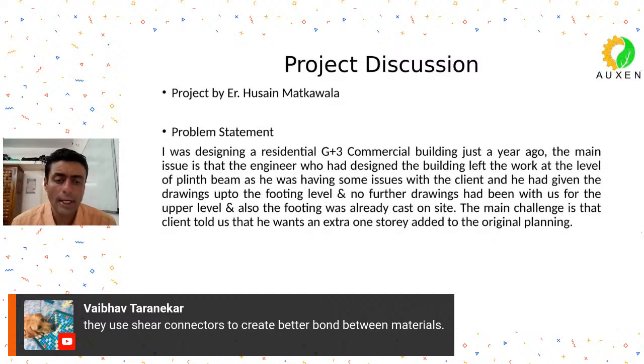It's quite okay. And of course, then you can provide some rings. So in the footing also, if you want to increase the plan area, and if you want to make that monolithic, or if you want to make that behavior good in shear, you can always introduce some rings in the footing. So that is another option that you have.